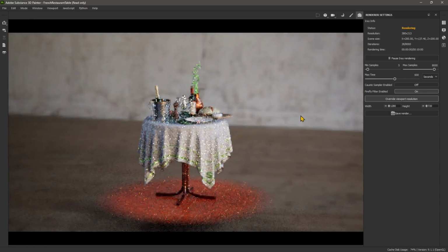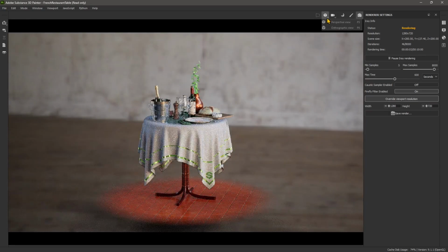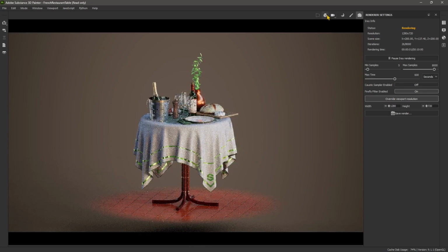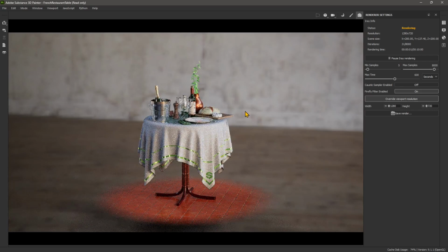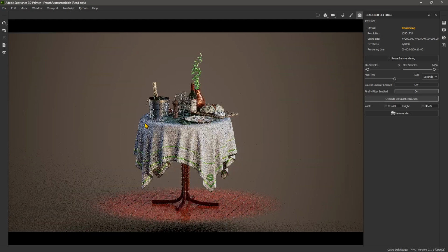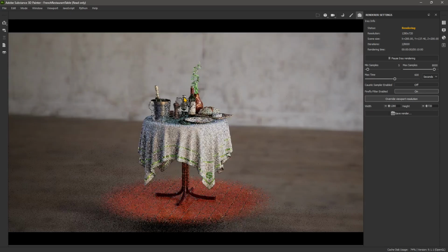And also we can change here from perspective to orthographic. Now this is orthographic. You can see orthographic will not show the environment right now. So if I go to perspective view, I can see the environment. So I can use the environment just for the reflections and for the lighting, and then just hide it. Or I can use it also as a background.